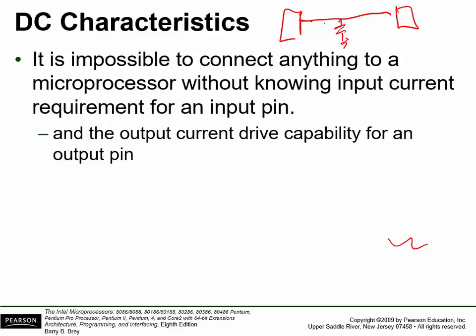And as you draw current through here, it's going to affect how rapidly the signal changes. If you have a signal that goes like this, what gets to the next point may look like this right here. You have this stray capacitance and the resistance of the wire itself.